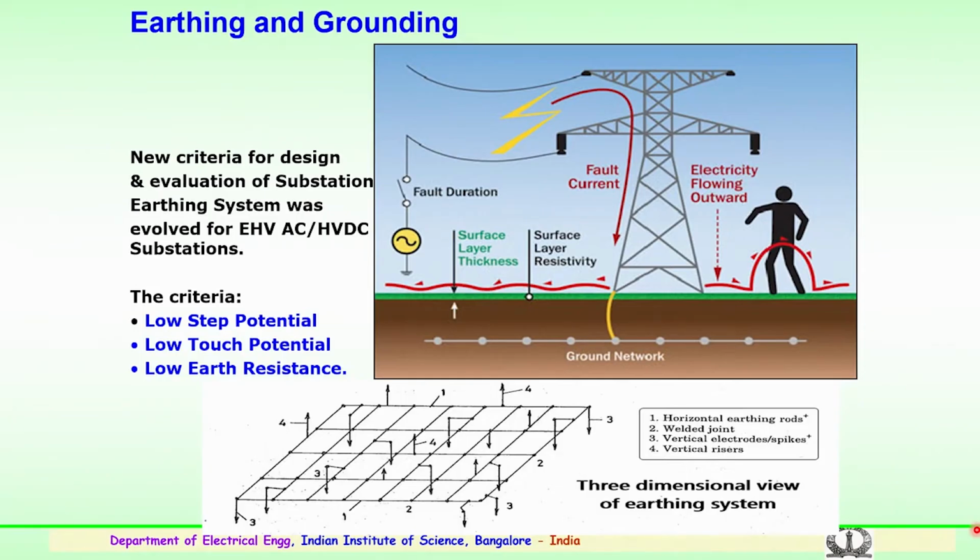So, that was about the electric and magnetic fields in the substation. It could be a high voltage substation, or a medium voltage or low voltage substation. Proper precautions are important: proper conductor management, clearances and necessary shielding will help to overcome the fields, both electric and magnetic. We will now look into the earthing and grounding aspects.